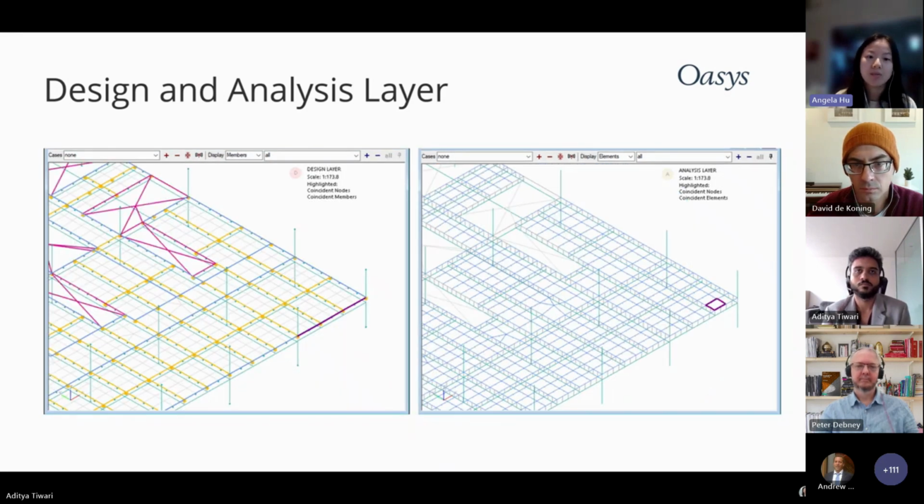This concept in GSA, you can apply to a really complex geometry or to a simple structure. So on a simpler building, for example, something you may do is first bring in the geometry from BIM. In BIM, everything is modeled: one entire column, one entire beam, the entire floor slab with voids. You can bring all of those in. And then what GSA will do is mesh it and create the finite elements needed for analysis. So if you needed to interrogate anything in the analysis layer, you can look at things like the connectivity on an element by element basis.